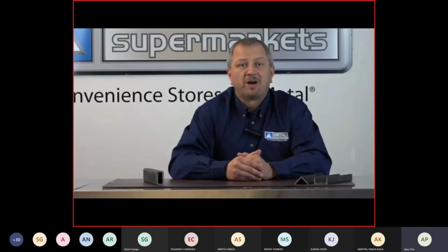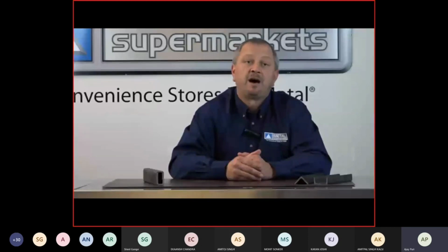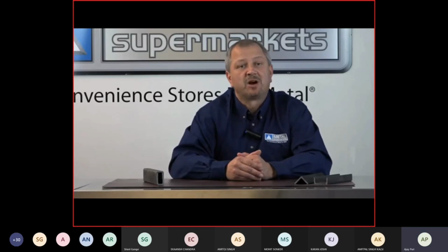High carbon steel, commonly known as carbon tool steel, typically has a carbon range from 0.61% to 1.5%. High carbon steel is very difficult to cut, bend, and weld. Once heat treated, it becomes extremely hard and brittle. Hopefully this has given you a better idea of the types of carbon steel. In the next part of this video blog series, we will look closer at the A in CAST, alloy steel.